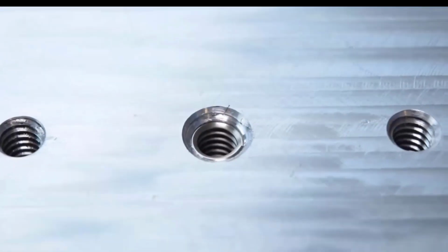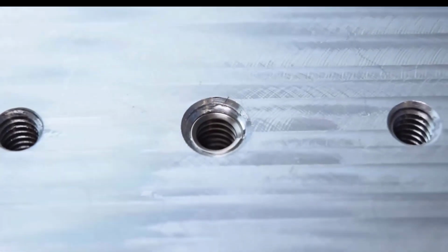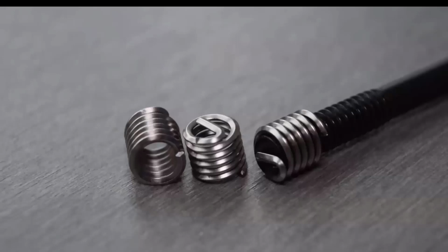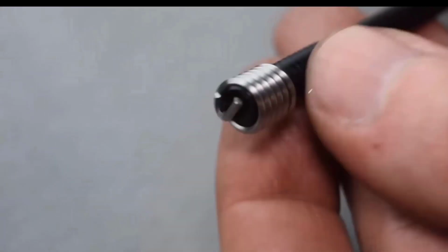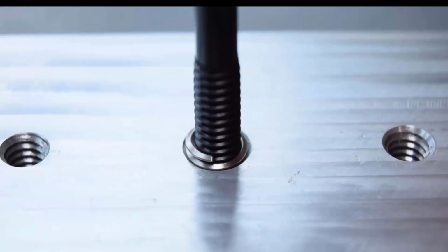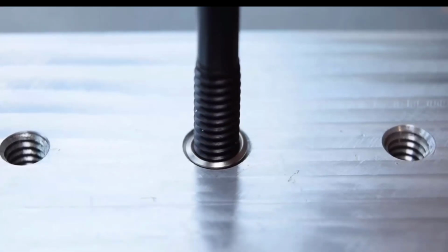If the tap threads in a workpiece ever become damaged, you can use a component called a helical insert, often sold under the trade name helicoil, to repair them. You drill out the original thread with a drill that's slightly larger than the major diameter, and use a special tap to cut new threads. Then, you install the insert with a threaded mandrel and break off the tang at the bottom.